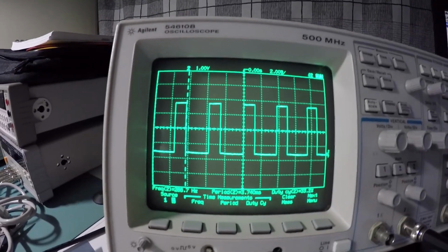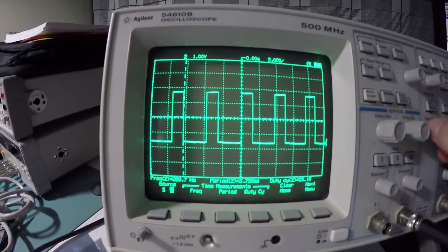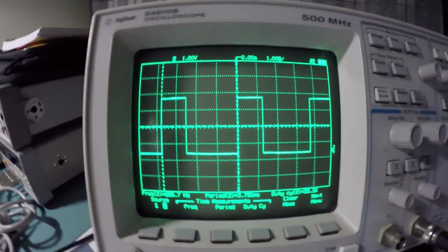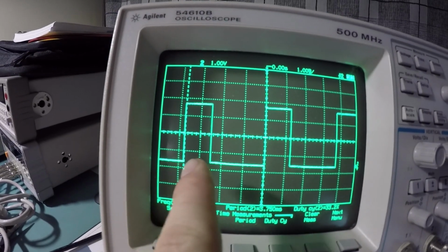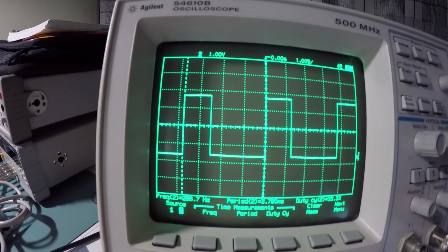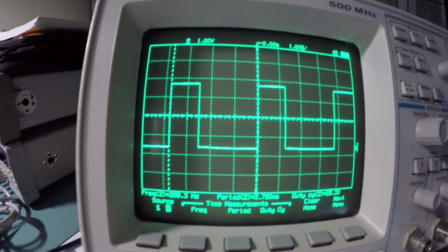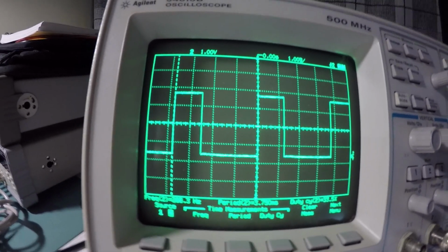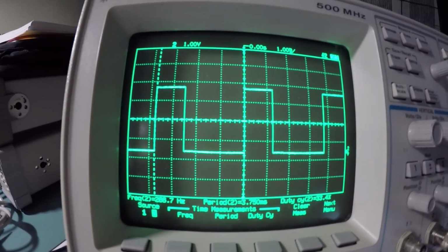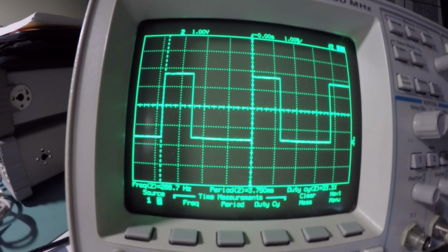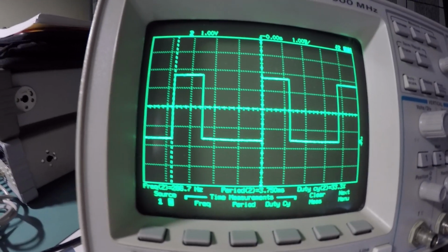Now the reason for this is because the period is being extended by each of the states within the LCD core's state machine. By running 3 states within that state machine, we're changing the period, the duty cycle, and the frequency.